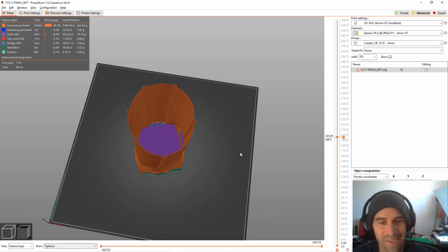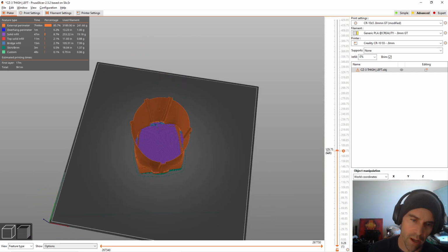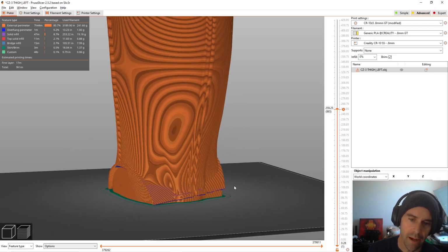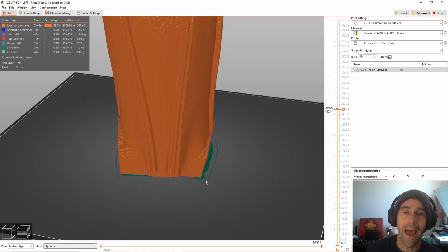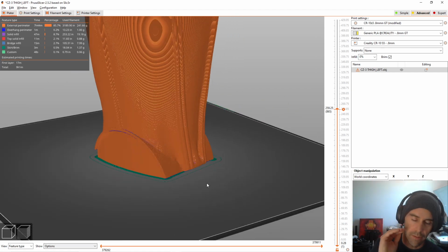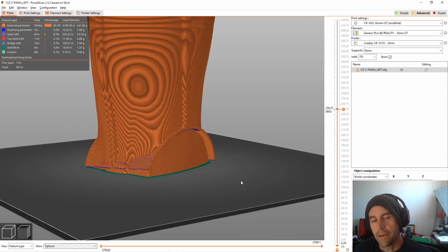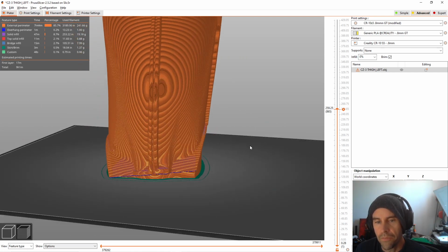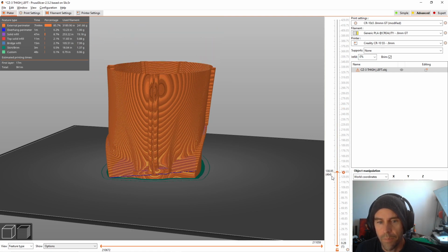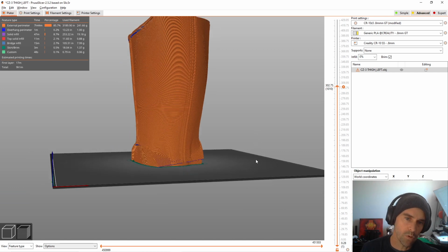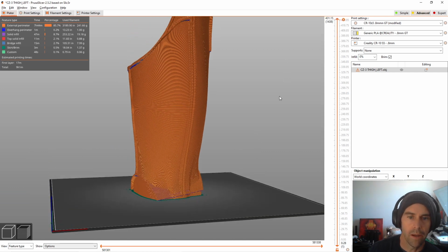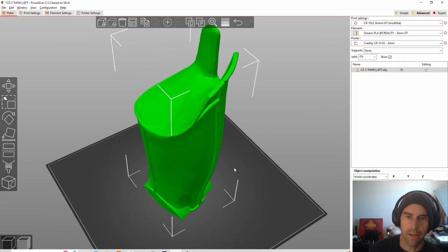Another thing you can do, if you're savvy with the 3D stuff, and I should have done this myself, is I could have added a few little standoffs here in the 3D software to act as support material. Like I could have basically integrated a support material into the part and saved all of this nonsense, and it probably would have saved a good half hour of print time. But yeah, anyway, those are my settings, a little bit of thoughts on this.